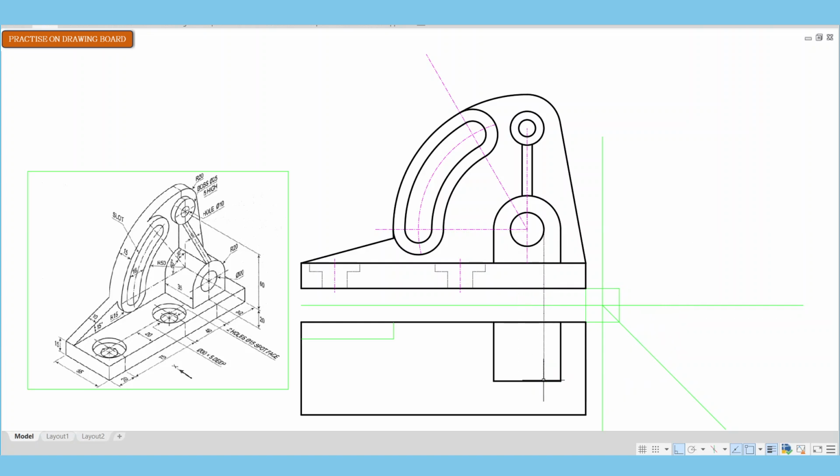And then the hole that goes through, I am projecting the hole downwards, but this time I would have to use hidden lines to indicate that there is a hole that is going through the protrusion. So that is that. And now I'll just draw my center line through.